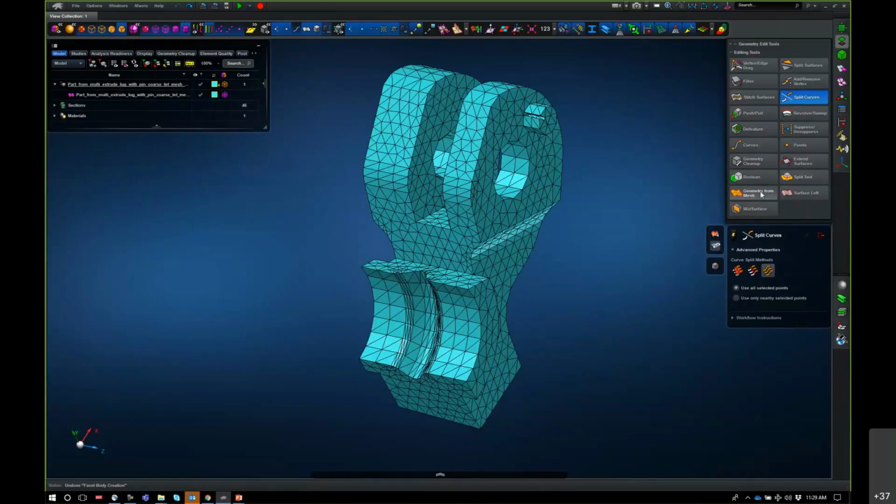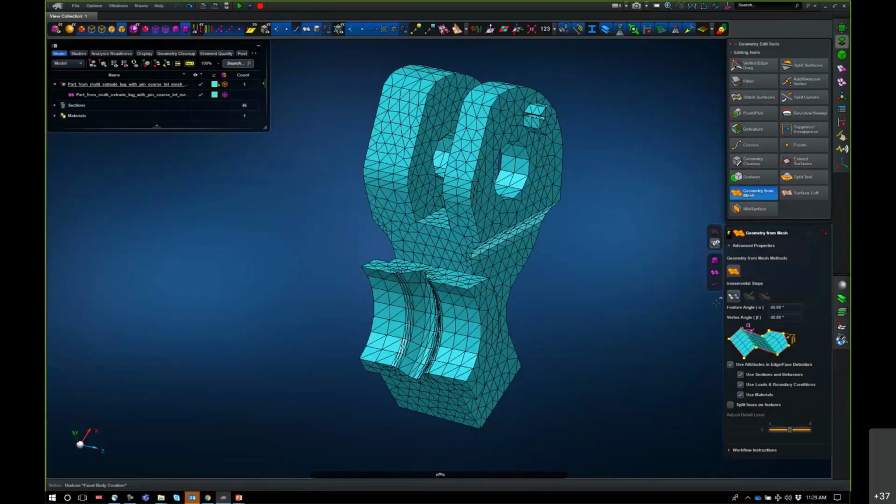So I'm going into the tool, same tool as before, and the beginning part of the tool is the same. If I happen to have attributes already in my model, these attributes can be loads and boundary conditions, pressures on faces. They can be curves or bar meshes. It will always split faces where there's a bar mesh, and it can be different sections or different materials. Automatically, using these toggles here, it breaks up my model using this information.